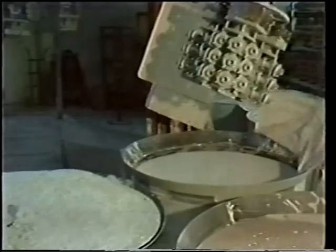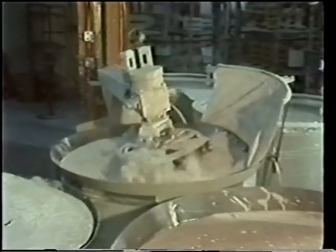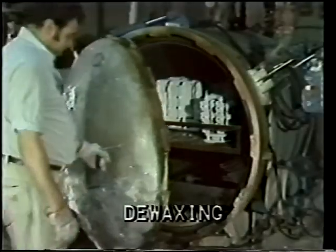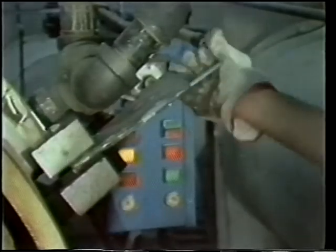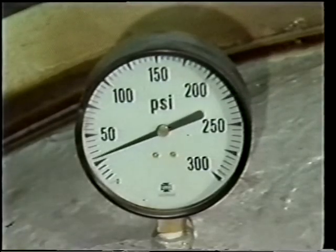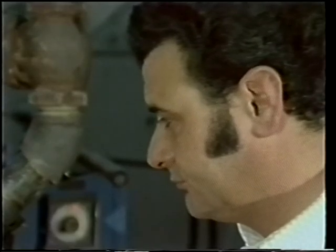Each coat is stuccoed with a dry refractory. The completed shell is called the investment. When the investment has hardened, the mold is placed upside down in an oven or high-pressure steam autoclave. With the ensuing high pressure and temperature, the wax pattern is melted and permitted to run out of the mold.